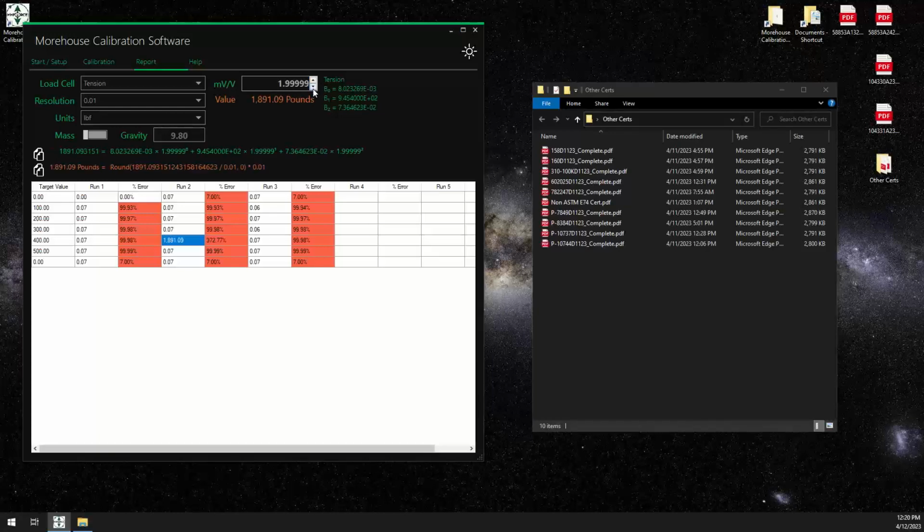I don't see the need. Again, it was something that, like Zach said, somebody asked us for, and Zach was kind enough to put it in. It certainly looks like rounding, and I would handle that through resolution and report that in my uncertainty. I don't think I'd do anything with the millivolt readings. No, it is not an offset. This is physically changing the captured millivolt per volt value. Yeah, it's rounding.